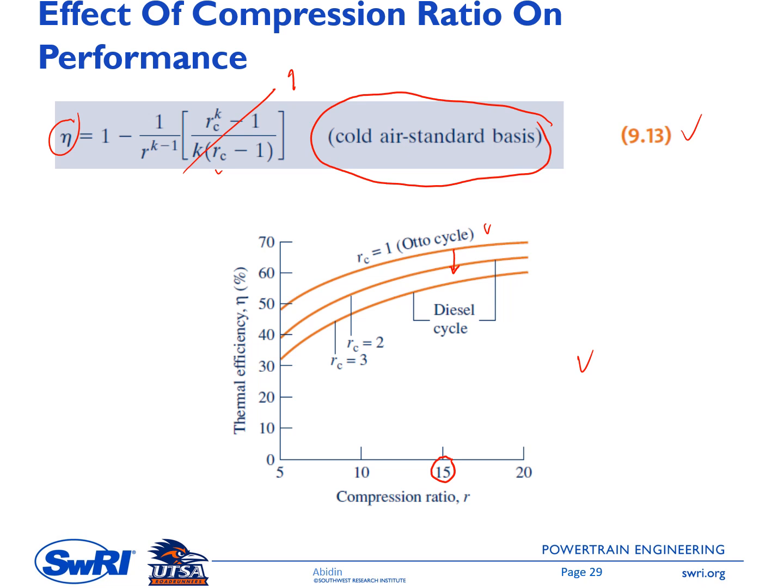But this is counterintuitive from what we see in the actual engine. We know that a diesel engine is more efficient than a gasoline engine. The reason is that a diesel engine usually operates at a very high compression ratio. And why can it operate at a very high compression ratio? Because there is no knocking issue in a diesel engine.